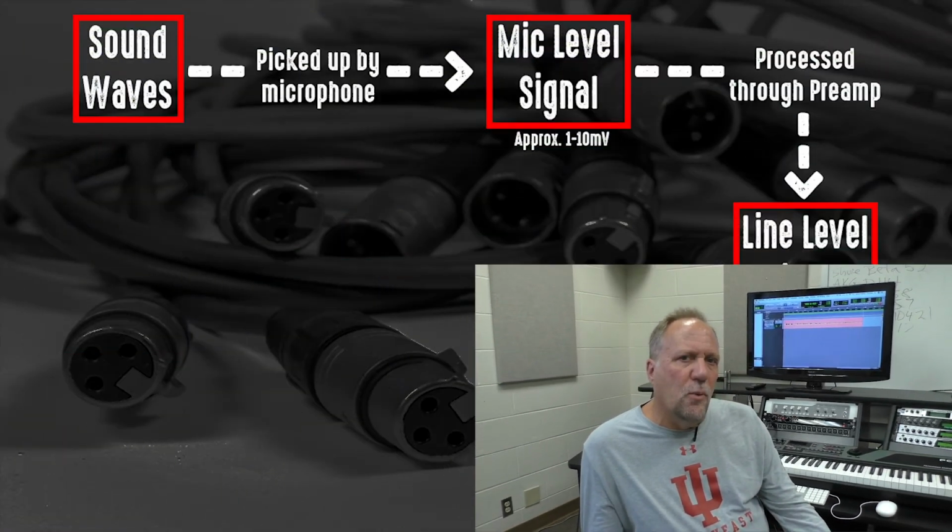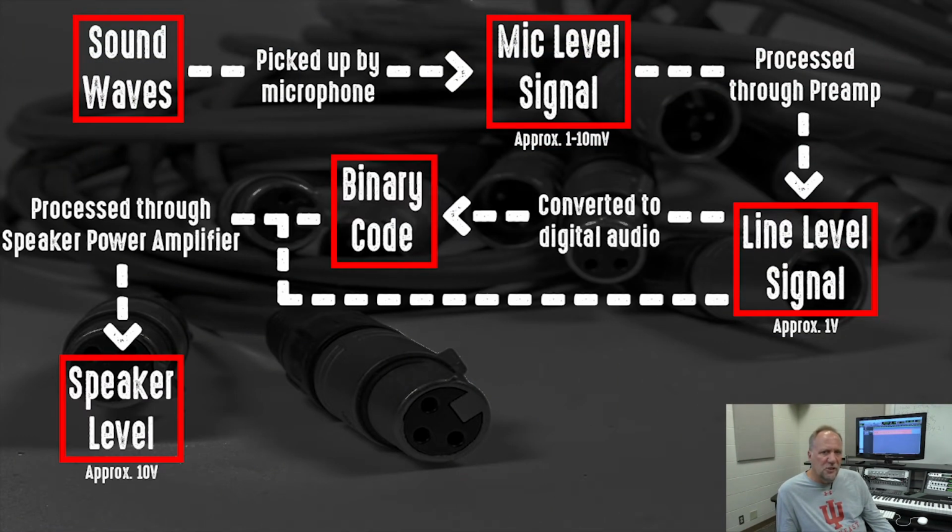Any kind of analog signal processing like analog EQ, compression, delay, etc. generally occurs when that signal has been strengthened up to line level. That way the electronic devices are less likely to impart distortion, interference, those kinds of problems into it, since the signal's already strong enough to maintain its own integrity. That is the point where the signal is converted to digital if you're doing a digital recording, or it also is used to feed the power amplifier, which is what runs the speakers.